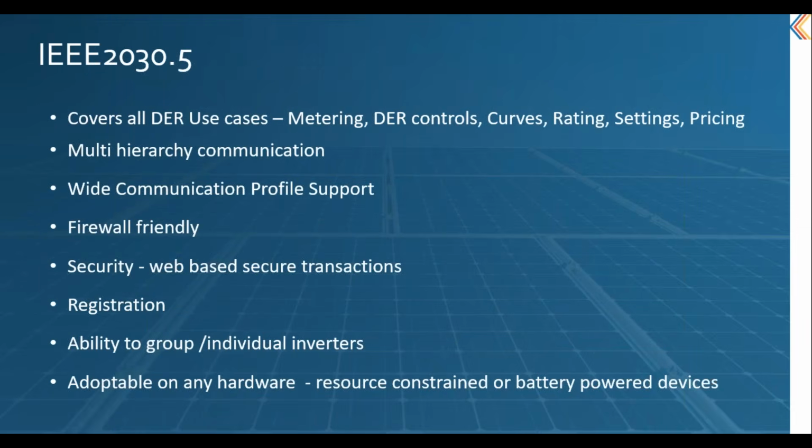So to overcome these challenges, there is an option called IEEE 2030.5. IEEE 2030.5 is designed to address the above issues. This standard is designed to connect or integrate consumer devices with the utility using widely adopted IP or HTTPS web technologies on a client-server architecture, where the client is in the field and gets connected to the server at the utility premises or DER site display units.